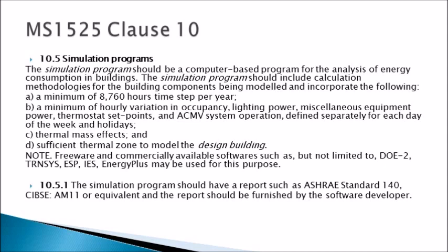Okay, and the software should allow the designer to divide the building into thermal zones. For example, if you have 10 rooms which you control the air conditioning differently, or some are not air conditioned, and so on and so forth. So the software must be able to reflect that. You don't want the software to only simulate the building as one big mass or big volume. For that, there are many software and freewares available, but you have to check the latest ruling on that.